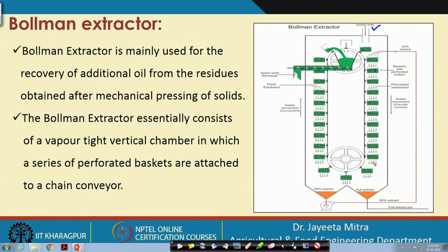There is a closed, airtight chamber of all the buckets, and the solid is coming into the bucket in a measured quantity. The 50% extract that we are collecting from this left arm is being spread on top of the fresh solids coming in, where the solute component is in full concentration. As these buckets come down, the solvent will percolate through them and the extract will collect at the bottom.